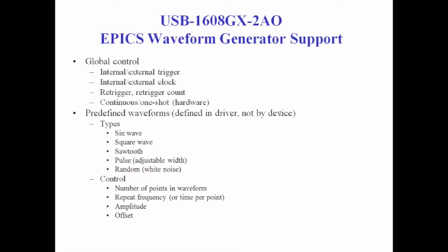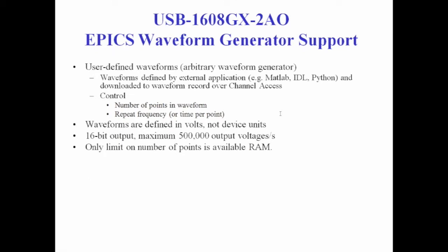It also has a waveform generator support where you can load a waveform and have it output that waveform. It has some predefined waveforms. These are done in the Epix driver, not in the hardware, like a sine wave, a square wave, a sawtooth, pulse, random. You can control these kinds of things, the number of points in the waveform, the repeat frequency, the amplitude, and the offset after you define it. And then it has support for user-defined waveforms for an arbitrary waveform generator.